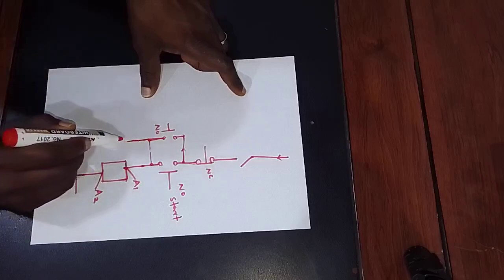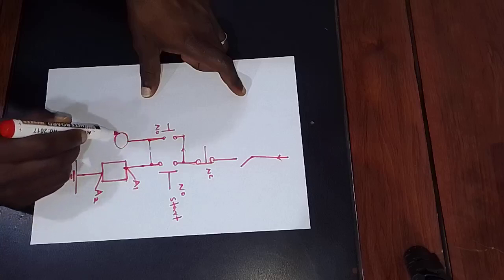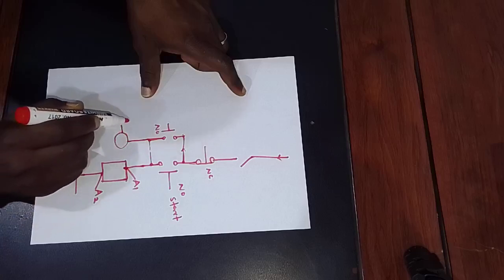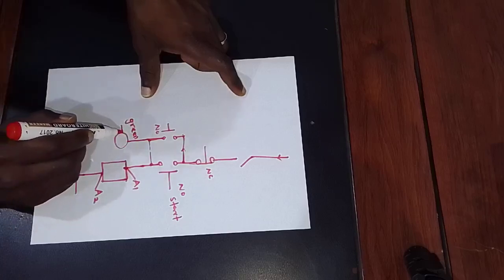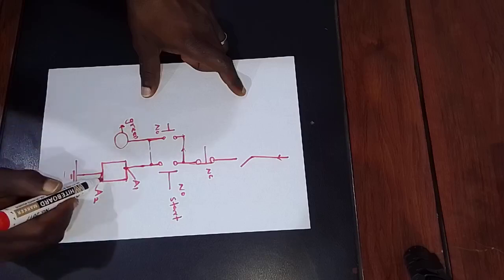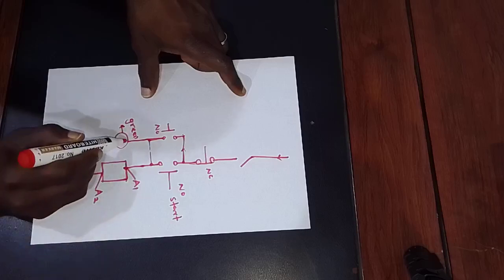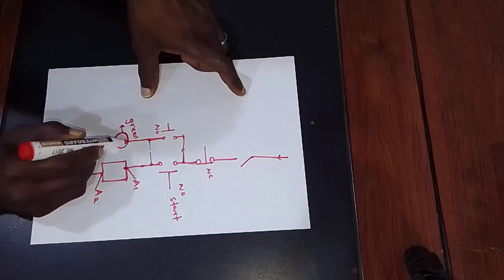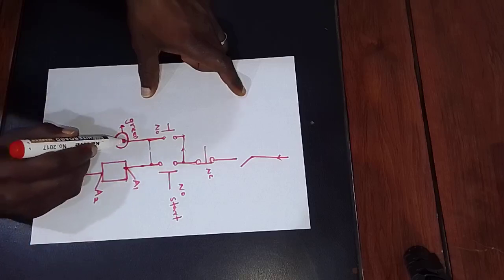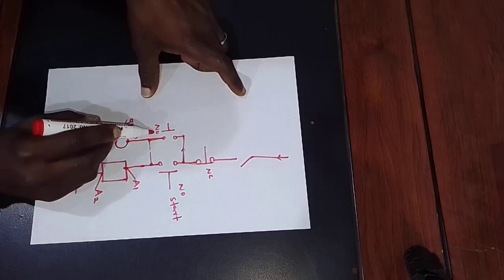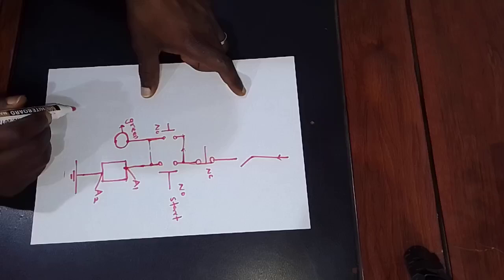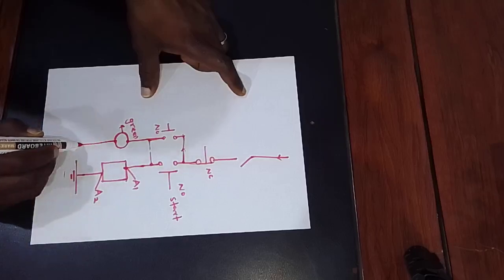Tap from here, connect to our green indicator light, which indicates that the contactor is energized. Like we all know, the indicator light has two terminals. One of the terminals is connected to the output of this normally open contact on the auxiliary contact, and the other terminal is connected to the neutral.